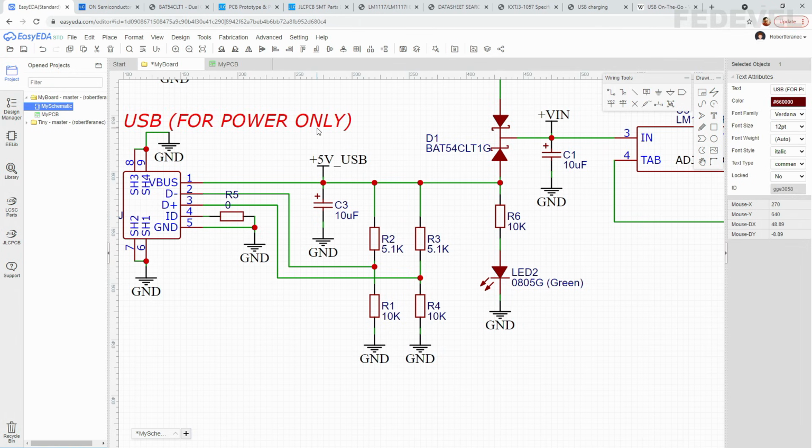I'm going to copy this, Ctrl+C, Ctrl+V. I will change the text to NF, like not fitted, and I don't want to make it so visible. Maybe use this kind of gray color. Okay, Ctrl+C, Ctrl+V. Oops, Ctrl+V, Ctrl+V.